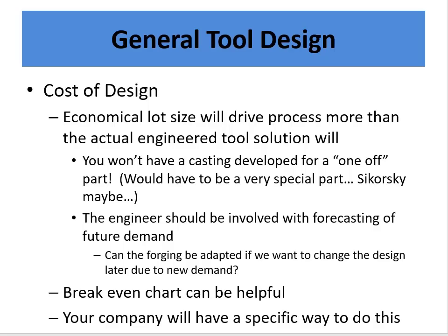And then the cost of the design. So the lot size will drive the process more than the actual engineered tool solution. That's usually true. You can come up with a really, really cool design for just about everything, but if it's not economical and it doesn't pay for itself, it's not really going to happen.